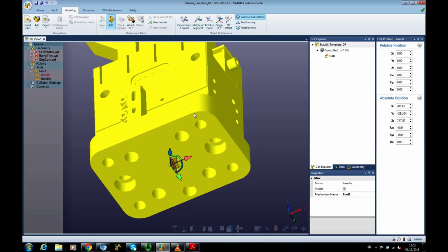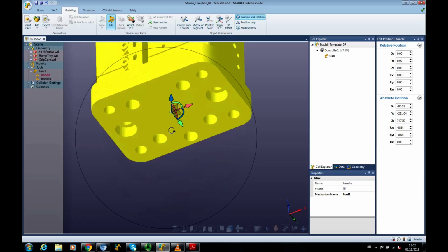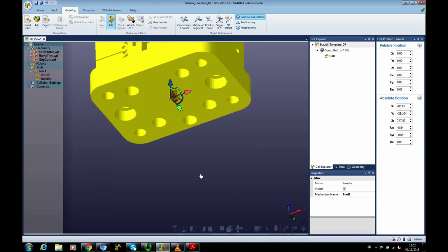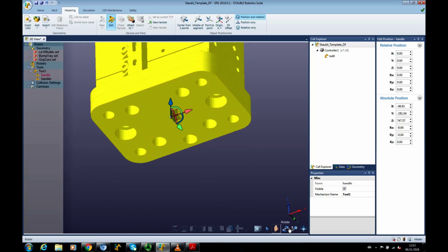Okay. Hopefully after quite a difficult trial and error, if I'm honest, you'll be able to select these. You might have to zoom a little bit closer. You're selecting these vertices here, and what should happen is the handle should jump into position. If you're going in this clockwise motion, that will mean that the handle is pointing, the axis is pointing in the right direction.